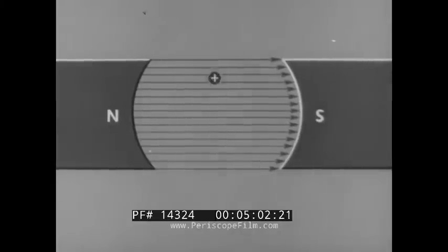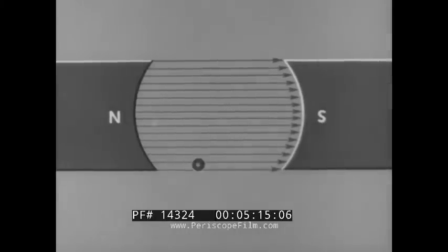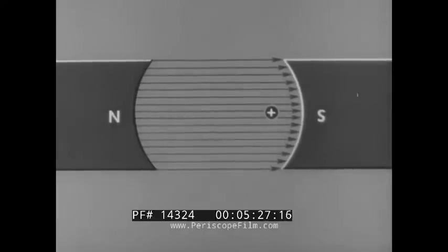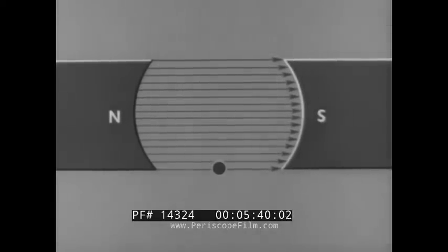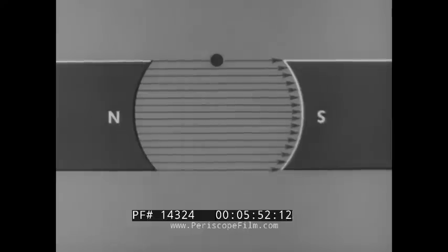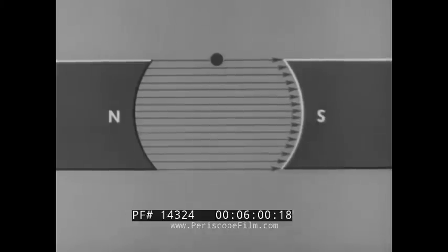But the conductor in an actual machine is not moving in a straight line, but rotating. When the conductor moves in a rotary path, the number of lines cut varies depending on the position of the conductor. As the conductor keeps turning, the number of lines cut increases, so that at a quarter turn or 90 degrees, the maximum number is being cut and maximum EMF is generated. Again, at 180 degrees, no lines are cut, no EMF. We reach a maximum again at 270 degrees, and finally, again at 360 degrees, no lines are cut. The conductor has rotated 360 electrical degrees.